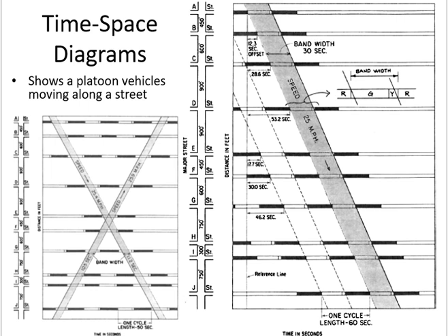Here the cycle length was 60 seconds. 12 seconds is less than the cycle length, no problem. 53, still less. Here it was 77.7, which is more than the cycle length. So 77.7 minus 60 is the remaining.